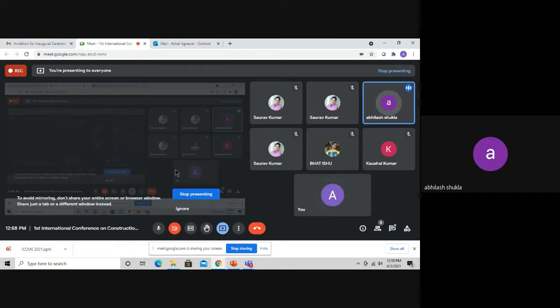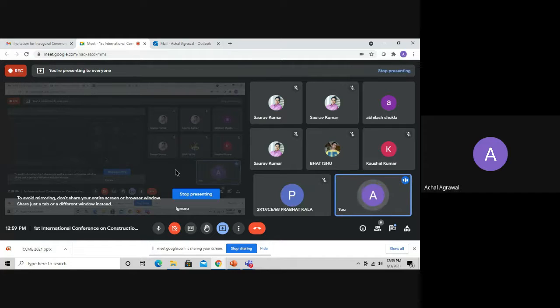Secondly, what is the role of VMAs, that is viscosity modifying admixtures, in self-compacting concrete? You haven't described any VMAs in your presentation. Although it's a review presentation, I wanted to ask what their role is. If you're using VMAs, we may avoid the superplasticizer. The role of viscosity modifier agents and superplasticizer is somehow relatable, right, sir?